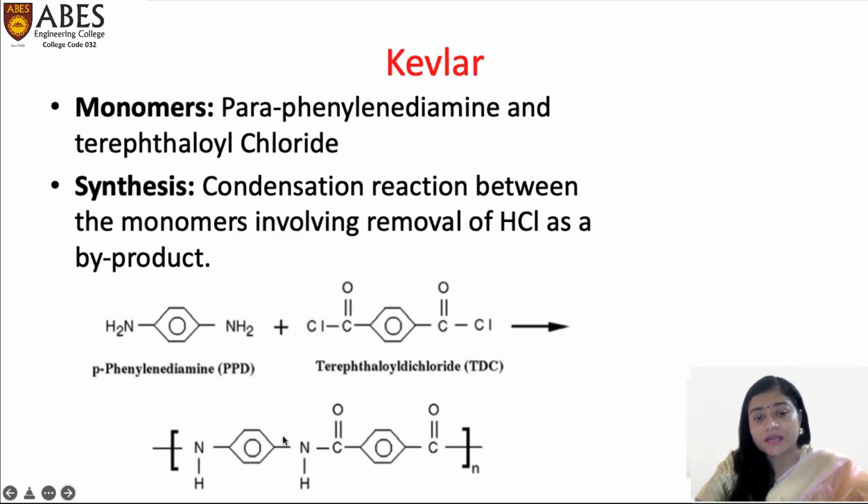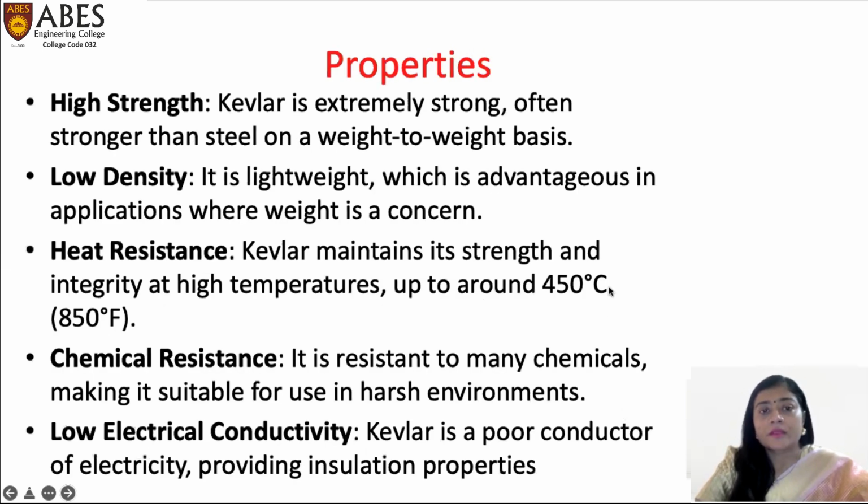You can see it has two aromatic rings extending the conjugation. Kevlar is a specialty polymer also because of its high strength. It is extremely strong, often stronger than steel on a weight-to-weight basis. It is lightweight, which is advantageous in applications where weight is a concern. It has high temperature resistance, that is, it can withstand temperatures around 450 degrees centigrade, and this is why it is used in firefighting suits also. It is resistant to many chemicals, making it suitable for use in harsh environments, and it has low electrical conductivity.